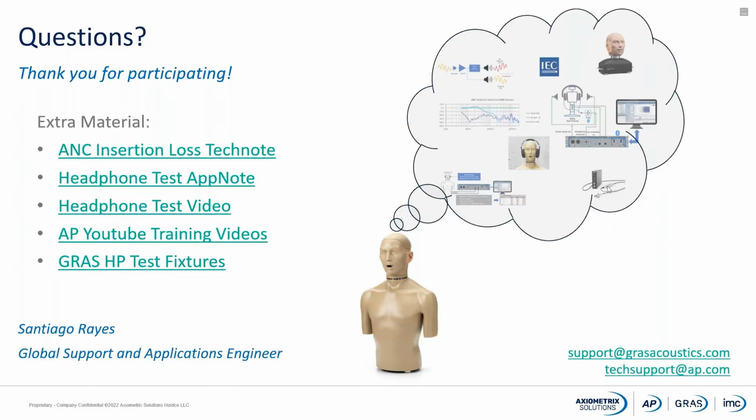Could we circumvent the head and torso simulator microphone noise floor 7 dBA spec given by the ETSI in an ANC measurement by increasing the generated noise level? For example, we can measure at 85 dBA. Yeah, you could do that, but that's the main reason why you sometimes need to use an ear simulator with a very low noise floor. It's in cases like the one I showed you during the presentation, where you want to measure the ANC circuit noise.